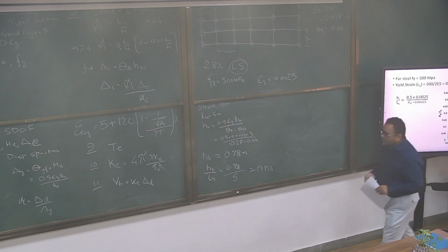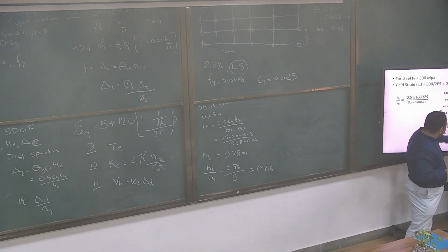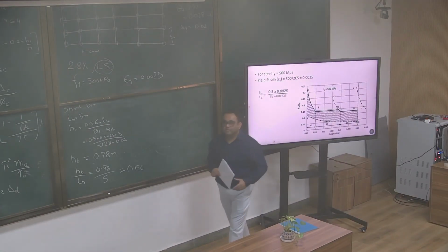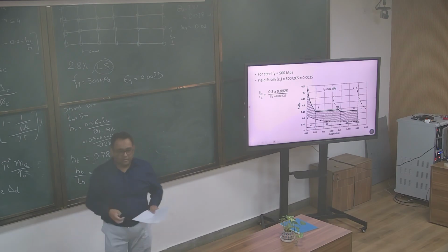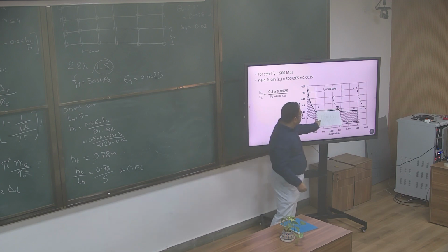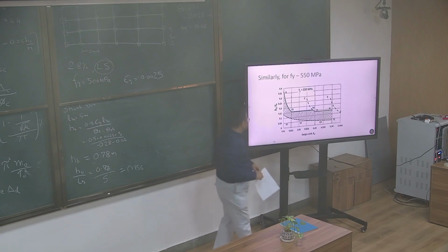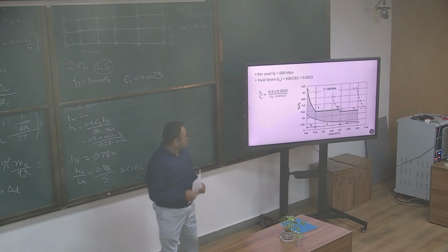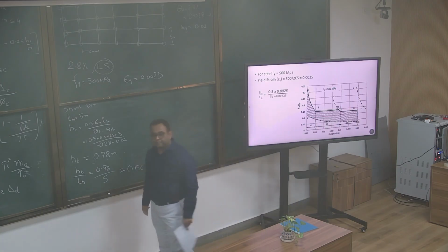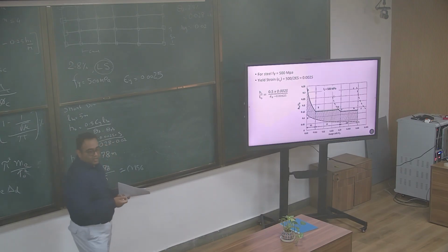So, if you look at our chart here for 500 megapascal steel, life safety requirement, our top HB over LB ratio is roughly 0.14, right here. So roughly 0.14 is our limit, but we are way above that for life safety. So we'll have to reconfigure the beam.